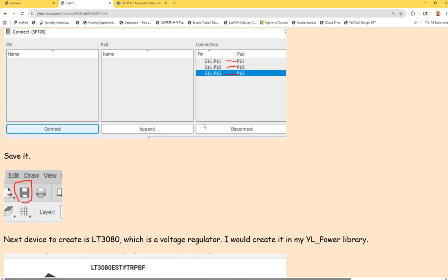So a lot of times, most of the components can be reused, like the resistor, right? The resistor symbol is always like this, 2 terminals. Doesn't matter if it's a rod or a surface mount, and you have all different footprints, 0603, 1206, which is the one we use, right? So they all share the same symbol. So if you have one symbol available in your library, you can keep using the same symbol for different components. You just make new connections to a new footprint, and then eventually rename the device as a different resistance for other things. It's really simple.